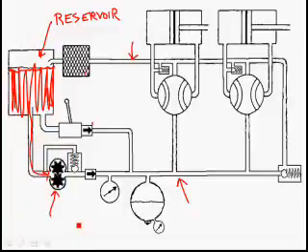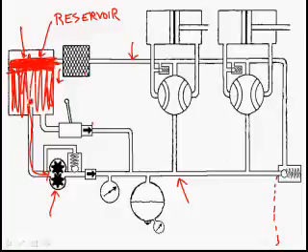The reservoir is needed to provide extra fluid for more than one reason. First of all, if we have a leak, drip, drip, drip, after a while the reservoir level is going to go down, so we need some extra fluid. The second thing is when hydraulic fluid gets hot, it expands. So you're always going to see some air on the top of the reservoir, so in case the fluid expands and gets bigger, there's still some space. So we need to have a reservoir to allow for fluid expansion and for fluid leaks.